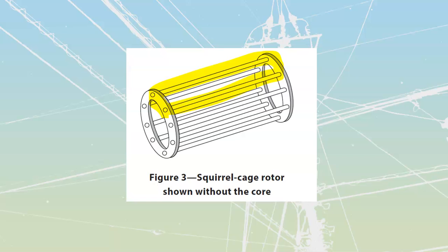You see that it is going to have few turns. Really, it's only got one bar going through here. And it's going to have low resistance. Few turns means high current. Low resistance, because this thing is going to be made out of aluminum or copper, which means we're going to get a lot of current actually flowing through these bars.